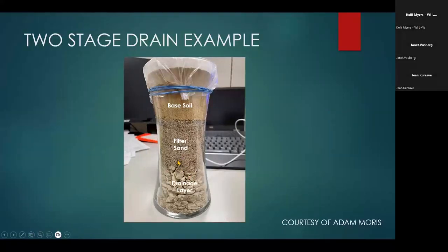But typically that sand may migrate in a little bit, but if this gravel layer is designed properly, like maybe a number 8 pea gravel would have been better here. I think this was more of a number 67, a bigger gravel, or not a big gravel, but a gravel. You'll get some migration down through there, but eventually that will stop, and the rest of this will be pretty clean for draining.